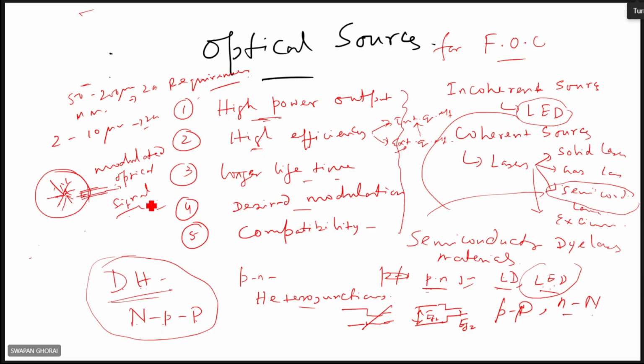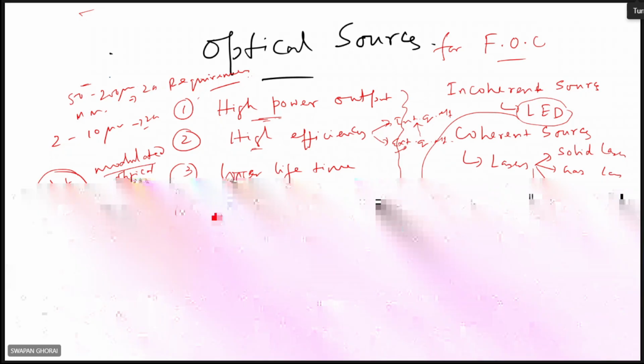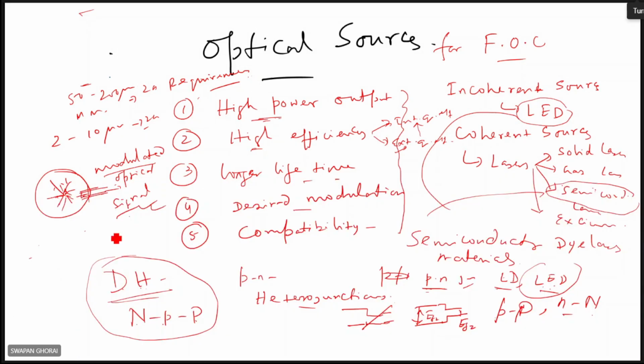So once you use the term modulating, that means certain kinds of modulation are there. You know the conventional modulation schemes: amplitude modulation, frequency modulation, phase modulation, etc., right? Not all those types of modulation are used in fiber optic systems. We'll see a specific type of modulation scheme is used. Intensity modulation is used in this case, because light is a very high frequency, 10¹⁴ to 10¹⁵ hertz. So amplitude modulation is not being used here. Actually, in this case, intensity is considered. So intensity modulation is used.